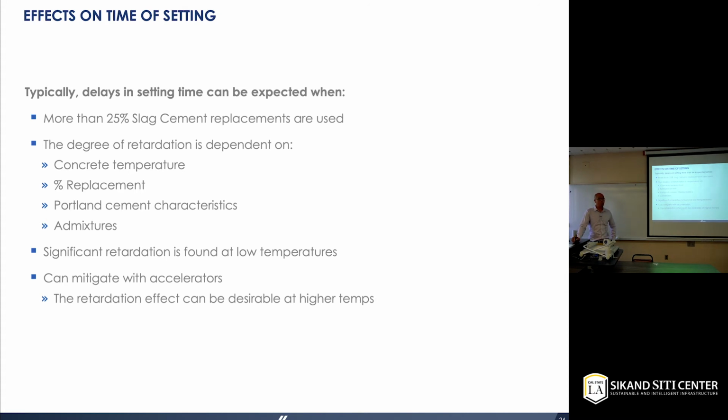As I mentioned before, having more chemical reactions taking place in your concrete mix does slow down the setting a little bit. If you're adding a high percentage of slag replacement, it's going to slow down the hydration process, but it also depends on the ambient temperature and the replacement rate.